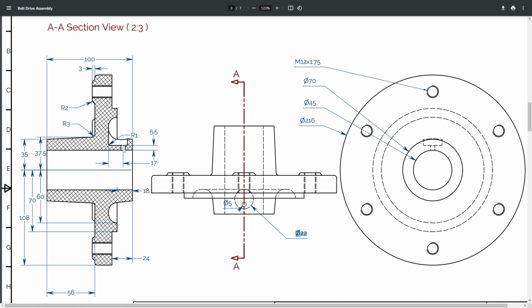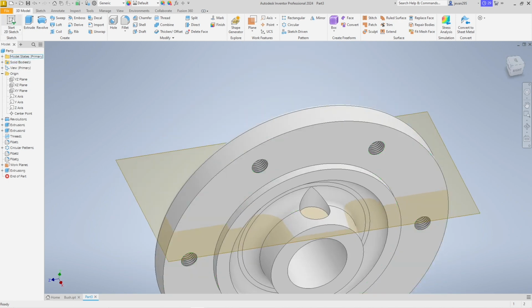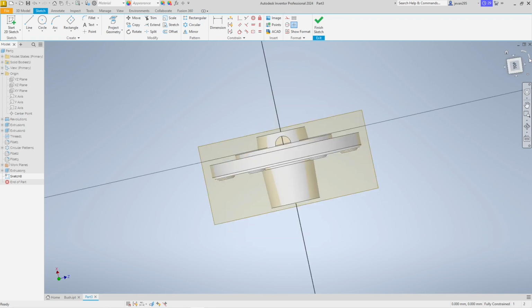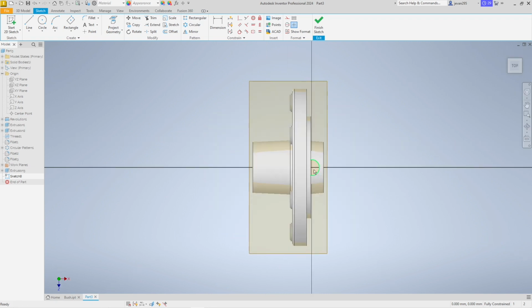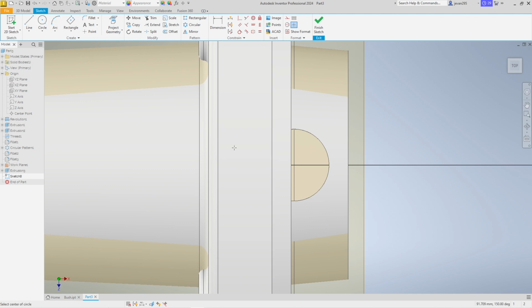We now need to create this little hole, which is really the easiest part. So we then want to start a new sketch in this circle here. If we view it from the side, it'll make it easier for ourselves. We then want to create the 5 millimeter circle just anywhere we want. Let's go right there, as long as it's on this line.